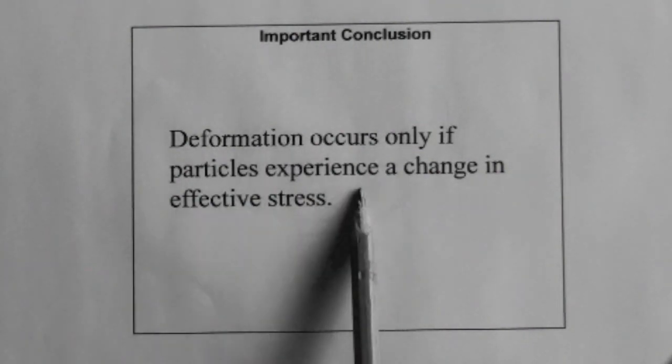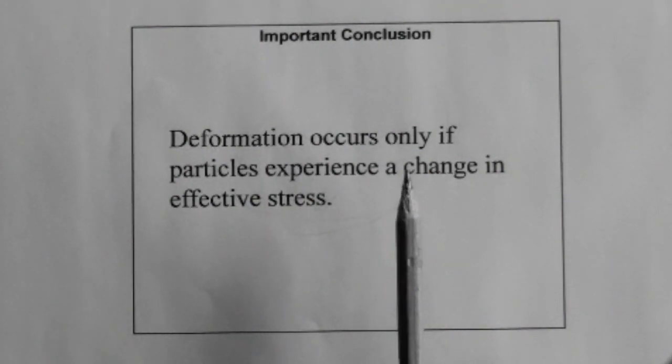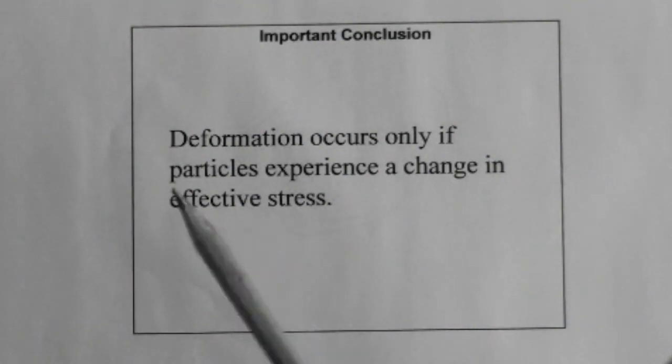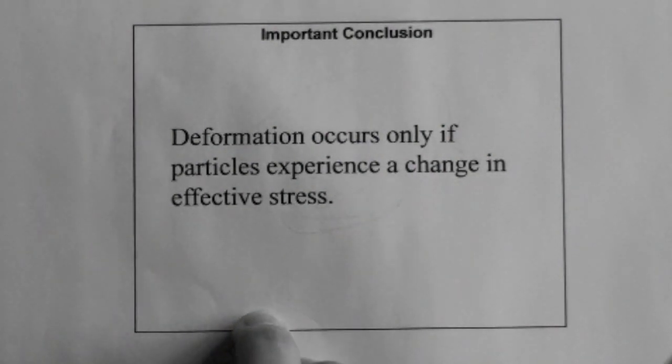This sentence is the summary of the concept, which is to understand that consolidation begins immediately after the load is placed. So the load is placed, meaning the fill, for example, is constructed on top of a site. Immediately the excess pore pressure is generated, and immediately, because the water is pressurized, the water begins to squeeze out, and immediately the particles begin to receive that load that is transferred as the water escapes.